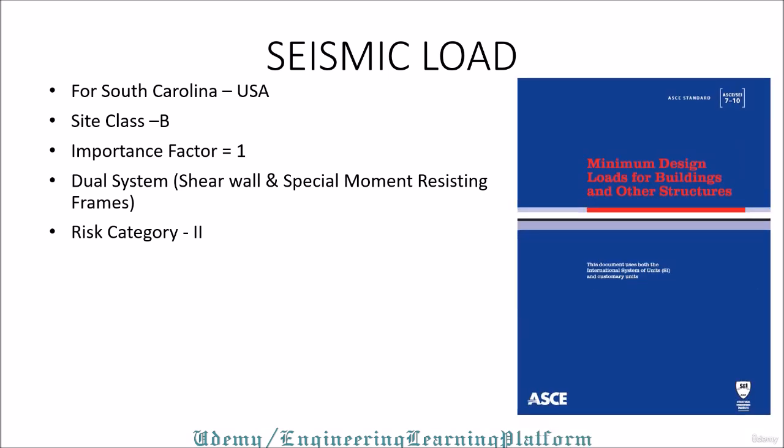We have to use ASCE 7-10 for application of load, or you can use ASCE 7-16. Very similar load defined criteria. So this is the table. We have to select the value of strength, response factor and deflection criteria. And let's go to SAP 2000 and define the load pattern for the seismic.